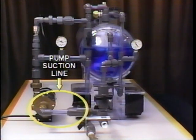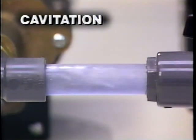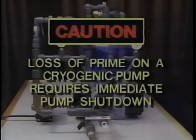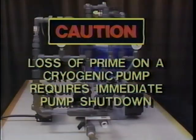The liquid in the pump suction line would begin to bubble or flash, causing the pump to cavitate or even lose prime altogether. Loss of prime on a cryogenic pump requires immediate shutdown to avoid pump damage. This is extremely important in the case of a liquid oxygen pump because a pump fire could result.